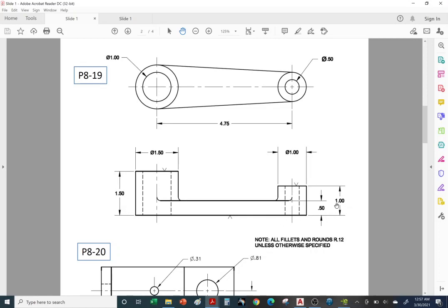We tend to want to group them together, but it just doesn't make sense to have the 150 over here on the right, because then we would need a long extension line. So we're going to take the oldest one, the 150, and just set it over here, because it just makes more sense to dimension to this edge or this vertex versus putting it here and extending our extension line all the way up to this point. So it's better to keep this one on the left and these two on the right. Cool thing is you have the middle sibling taking care of the little sibling.